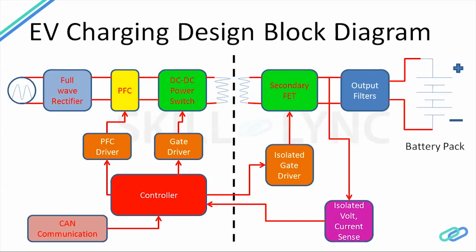So at the input of this DC stage, there come various types of topologies. Right, topologies like push pull topology, half bridge topology, full bridge topology. In the full bridge topology also there is phase shift full bridge, LLC type of converter. So based on our applications and requirements, we have to make sure which topology will best suit us based on the precision level, efficiency level, cost perspective. Everything we have to consider.